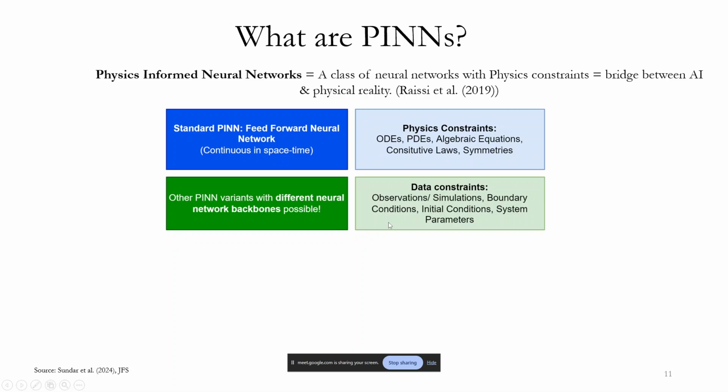They had to use the governing equations of 3D hemodynamics flows, which is nicely governed by your Navier-Stokes equations. This becomes your physics constraints, and then there's a continuity equation, etc. I'll not go into the details, but they trained a PINN model with spatio-temporal coordinates as inputs, and the outputs being your scalar concentration, velocity and pressure. They had initial conditions and boundary conditions, which in this case was just a scalar concentration. They had to infer u, v, w, and p, which is a very hard problem because you only have the scalar concentration, and you assume that it follows typical transport law and is interconnected with your momentum conservation and continuity equations. With this, they trained the network to recover the reference velocity and pressure as hidden variables.